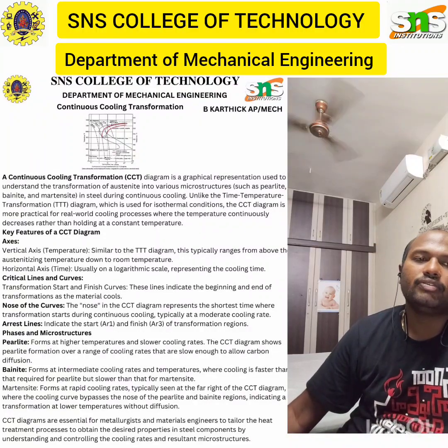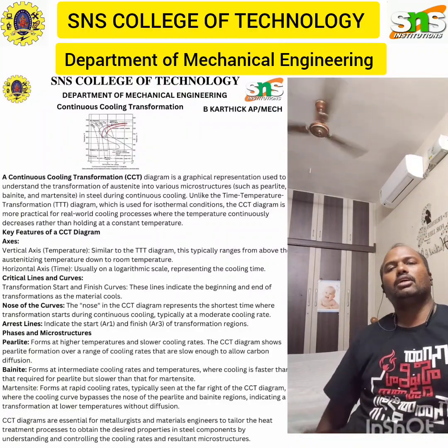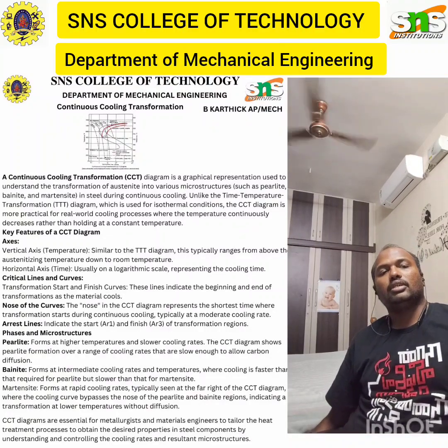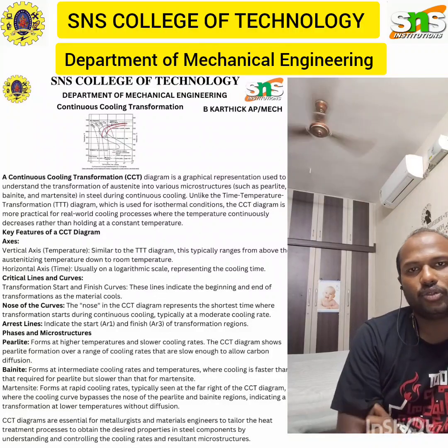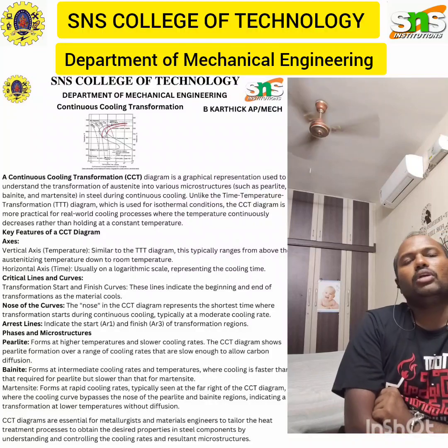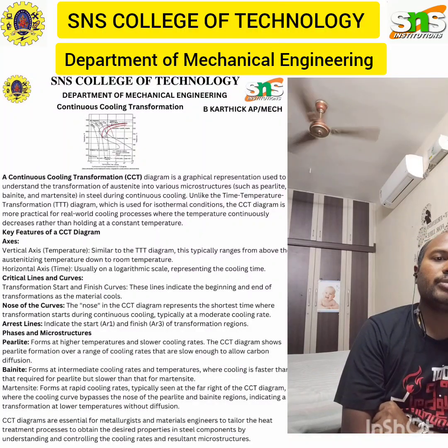In failure analysis, investigating failure by comparing actual cooling rate and resulting microstructure against the prediction of the CCT diagram. When compared to the TTT diagram, CCT diagrams are more applicable for real world scenarios where cooling is continuous, unlike the TTT diagram which assumes isothermal conditions. In cooling rate, the CCT diagram illustrates the effect of different cooling rates on microstructure, whereas the TTT diagram shows the effect of time at constant temperature.